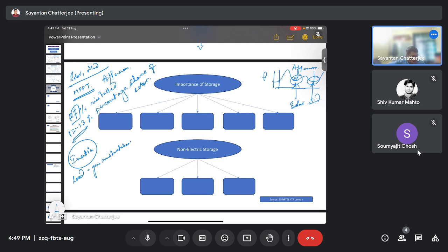So we'll have to keep those generators, because again an evening peak is there. During those evening peaks, the renewables are uncertain, so that's the problem. The spinning reserve value has grown very high, and that is creating much more of a problem here.